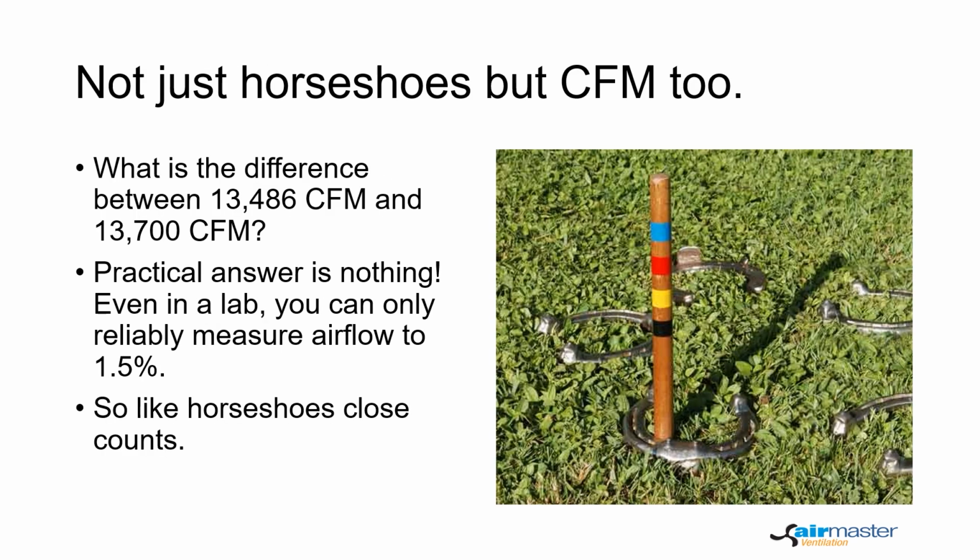I'm constantly amazed that engineers who should know better often ask for a fan that provides, for example, 86,411.6 CFM. Sometimes I just ignore this as I don't want to insult them, but if I know them at all, I ask them how they plan to measure this. The simple fact is that airflow just cannot be measured that closely.